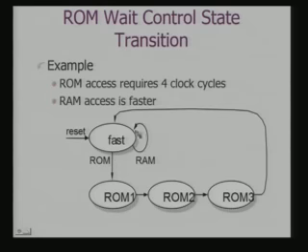So, if it is a RAM, I shall always be in the first state. If it is on the ROM, I have to take care of 4 states. So, my wait signal should be low, active low for 4 states, so that the system waits till it gets the data from the ROM. So, this is basically my control logic defining FSM.